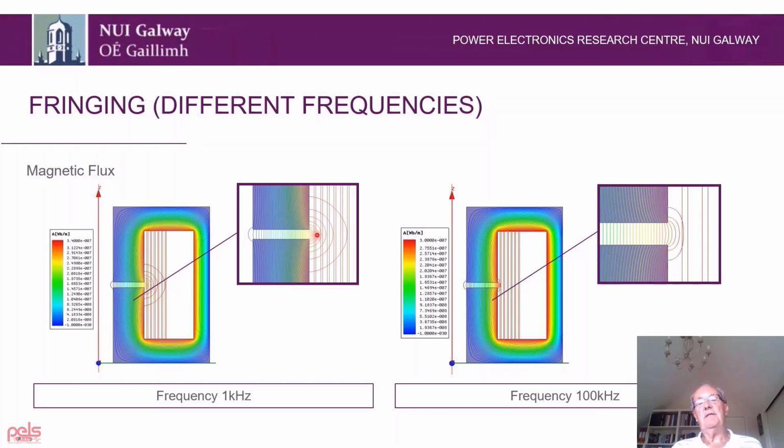This is exactly the same as the issue we had with the skin depth at low frequencies in our single conductor. Now, if we go to 100 kilohertz, what will happen is we'll have eddy currents flowing in these conductors here to block out the magnetic field. This is just like a Faraday shield, and these eddy currents will create losses.